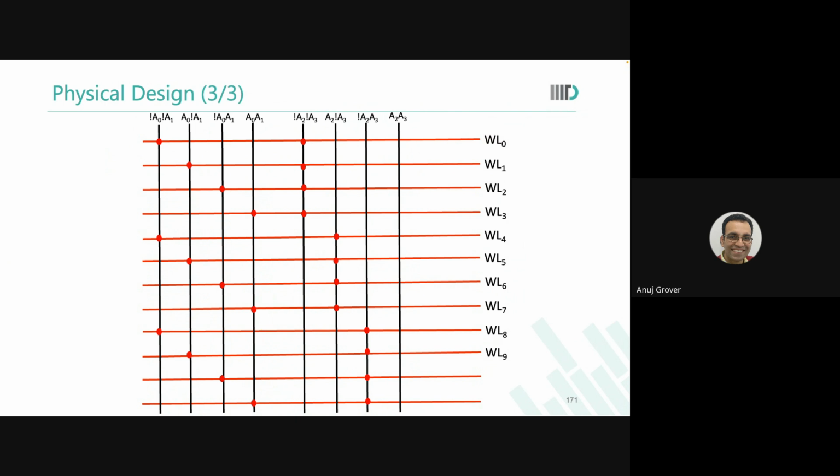Well, when we do programmation here, it will be the number of layers we are using in the device program. So you anyways need metal 2 to route your pre-decoded address lines. Yes. Otherwise, how will that information go up there? Metal 1 is there for local connects. Only in metal 2 you can bring. I'm just saying that for metal 2, you just change the location of where the via is dropped.